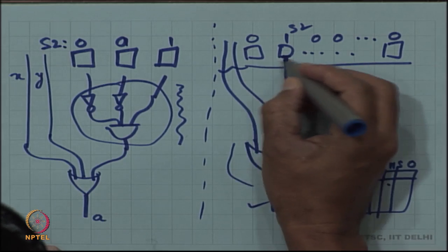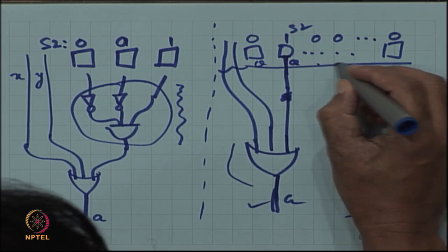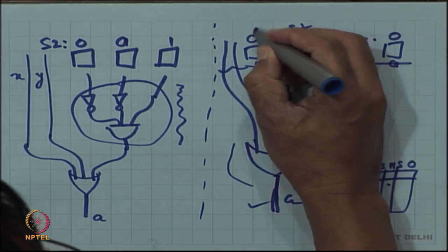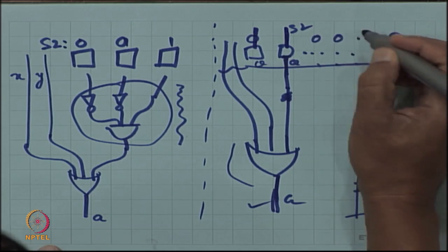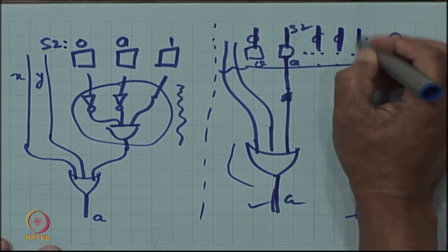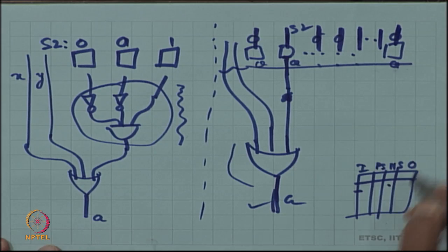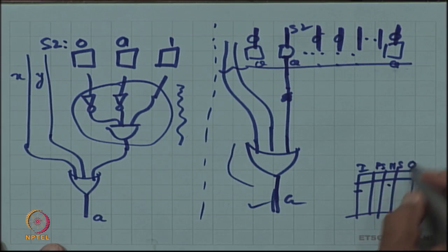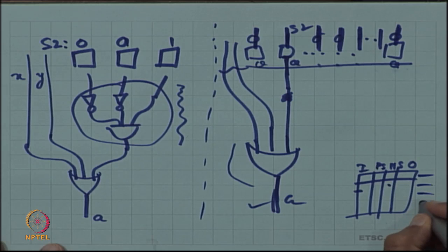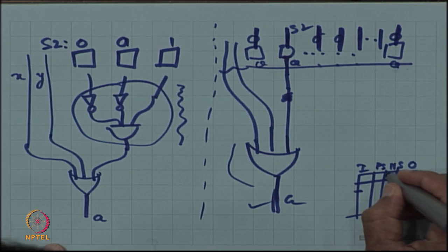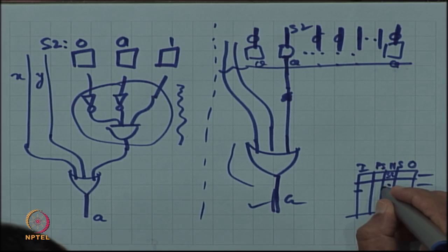See this 7, these are the Q outputs of the flip flops. The input D values do need to be provided, right. How do I provide it? I pick up from these rows all the rows where, let us say, S3 is the next state.